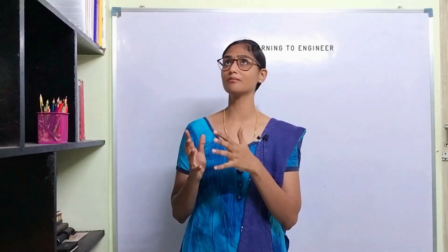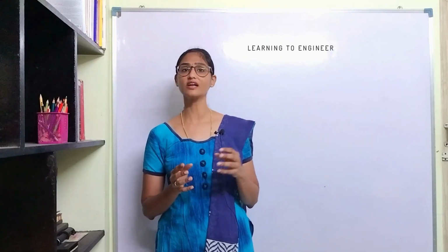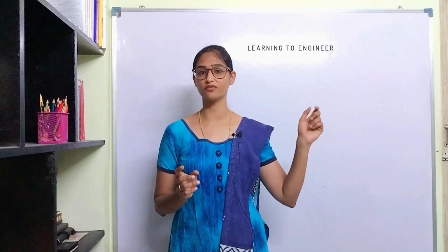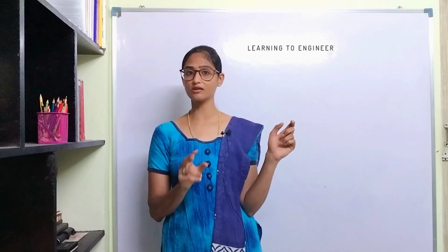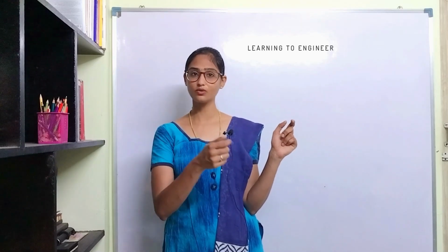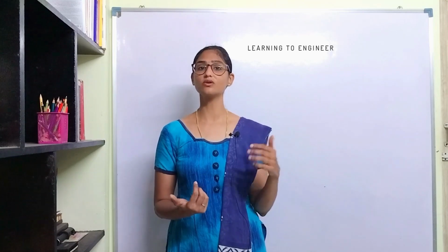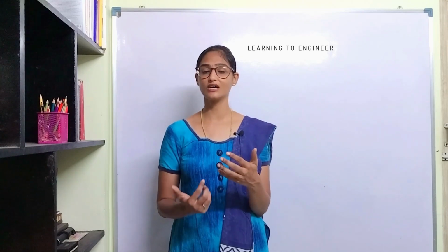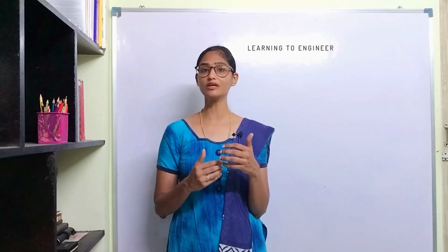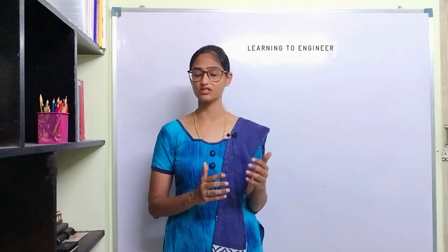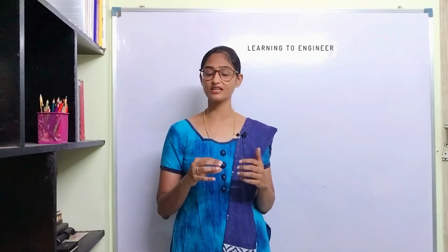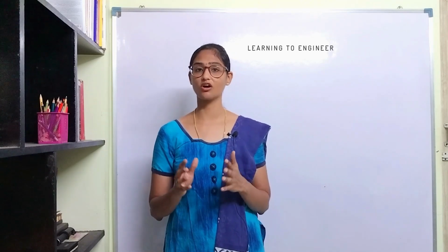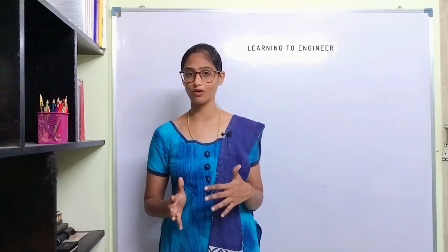Let us say, for example, you have a power supply circuit which you tuned to 5 volts, and you want 5 volts to be extracted from the terminals. There will be 2 or 3 terminals available in this power supply where you can extract the voltage. There will be one connector supplying the power of 5 volts to all the 4 terminals, and they will be individually isolated by voltage buffers, so that the circuit that you connect to this terminal doesn't really affect the input circuitry, because it offers a high input impedance and 0 output impedance.